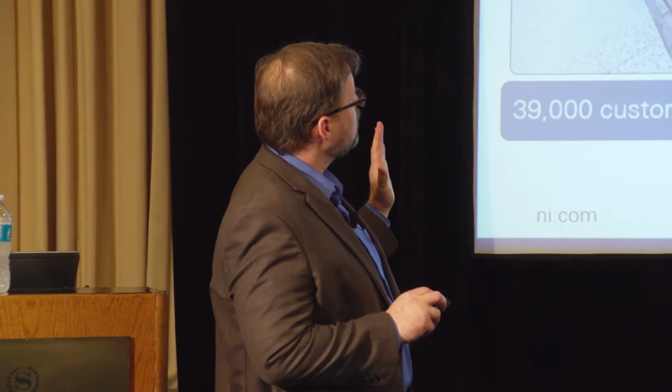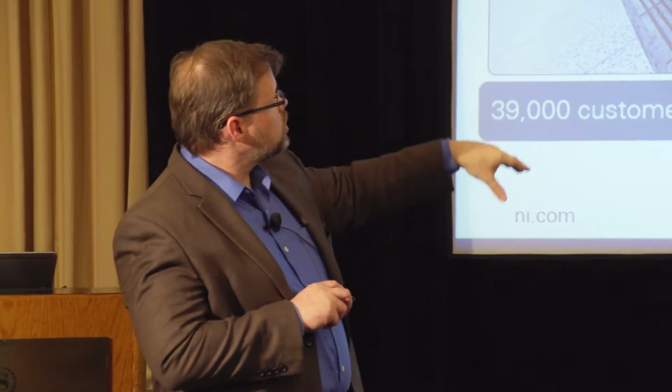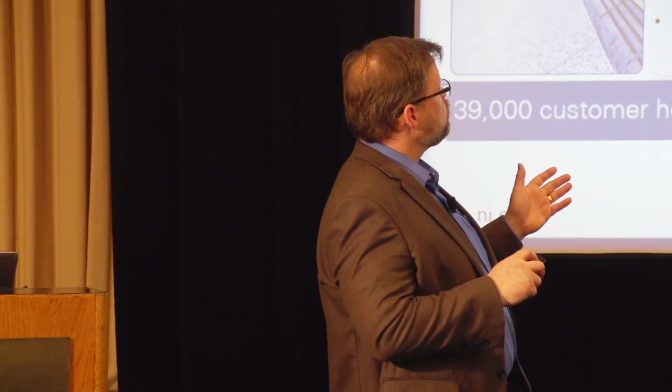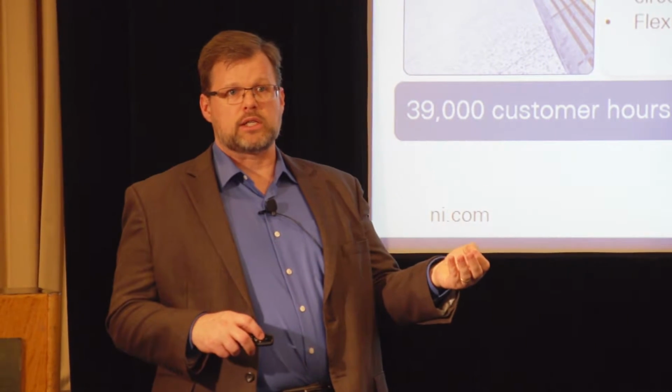the ones I've shown here. In the case of Firefly, if I go back, or we'll just go back to London Underground, this is more of a packaged version of that same architecture where the modules are I/O modules, where people can hook sensors and actuators, and communication protocols like CAN or LIN or FlexRay, which would be used to automate a machine. In this particular system, there's a dual-core Atom processor from our friends at Intel, and then there's a Xilinx FPGA in the backplane.